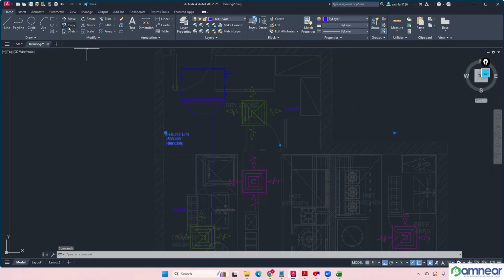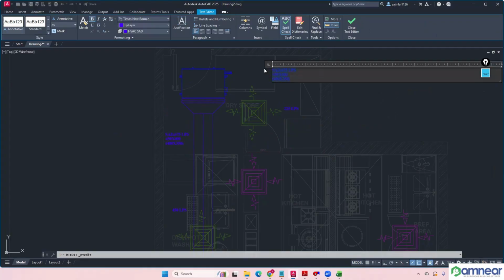Okay, so let me make the plenum box. Labeling everything we can do perfectly later. So the plenum box 350 mm into 350 into 350 mm. Which one is height? Height is 350 only. So flexible duct 300 dia, one number. The flow rate is 225 liter per second.